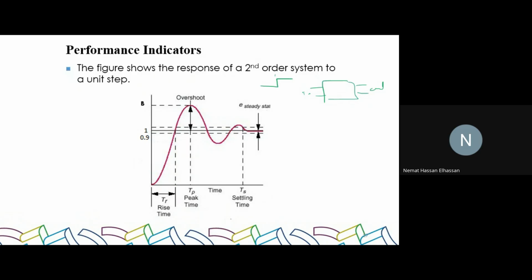And this is an example of a unit step response where the input was a unit step, simple line from 0 to 1. And this is your output. It starts with an overshoot, fluctuates and stabilizes. So you can tell that this system is underdamped, right? And based on this unit step response, there are other performance metrics that we can evaluate.